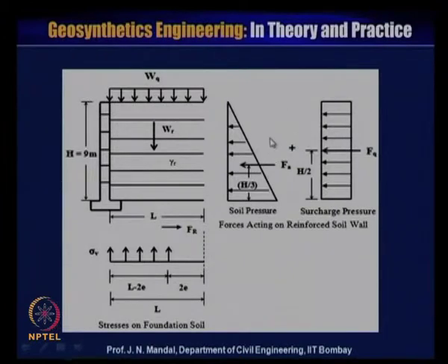So, you first have to consider whatever forces are acting on the wall. The forces acting due to the soil pressure, forces acting due to the surcharge pressure. If there is any live load, that also you have to take into consideration in the design. If there is an earthquake in a seismic zone, that also you should consider in this design.